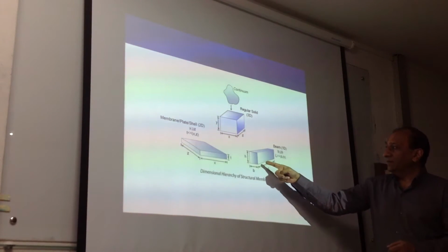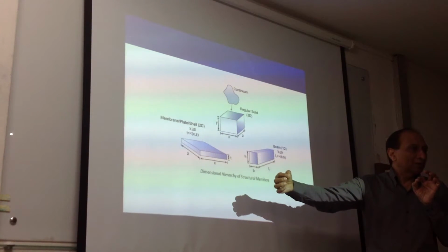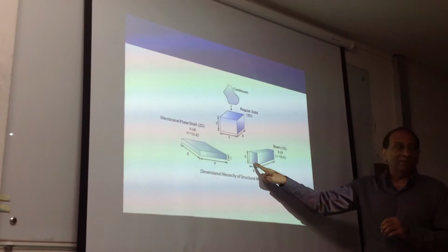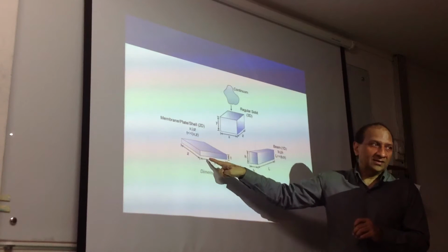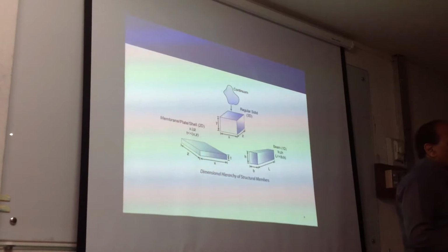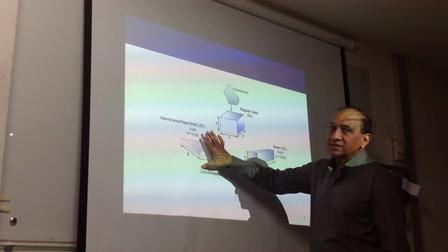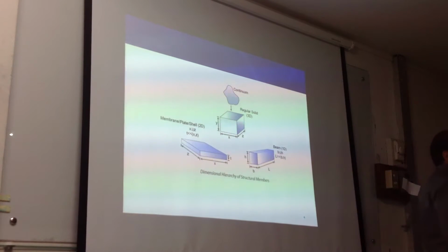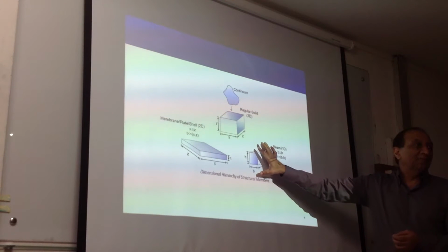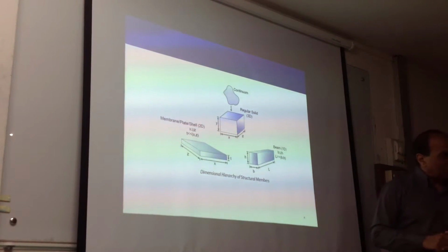When we say 1D, that means only the length of the member is modeled or considered. Other things become a property of the cross section. Here, 2 dimensions are considered, and the 3rd dimension becomes a property. It is not actually considered. Which means no matter how thick this thing is, if it is a slab, we still design it using the same approach. Similarly, no matter how big this section is, if we call it a beam, we still design it using the same approach. And that creates a big problem.